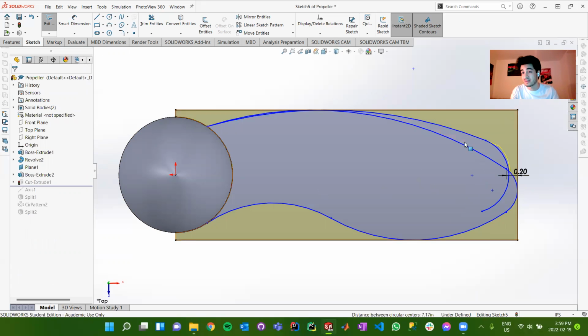You can essentially play around with it for yourself. I'd recommend trying to either recreate this shape or something a bit more unique. And from there, you just create a closed contour such that you essentially have an outline. So I'm going to get rid of these shapes that I just created because they're going to mess up our extrusion. So we can get rid of that. I'm just pressing undo here. Cool. And essentially from there, we have this outline now. What do we do with it?